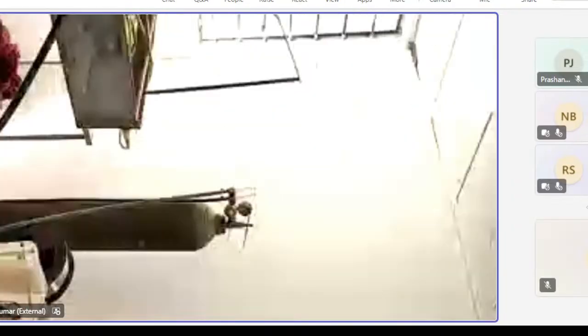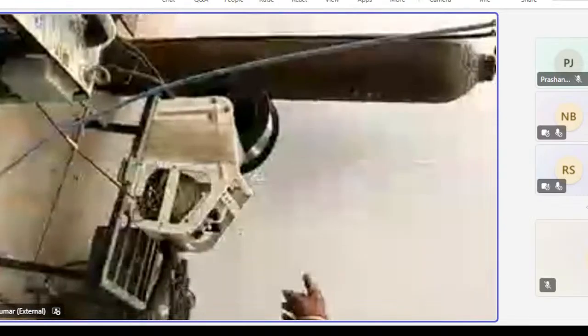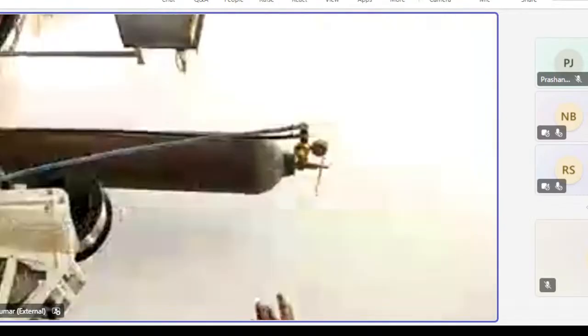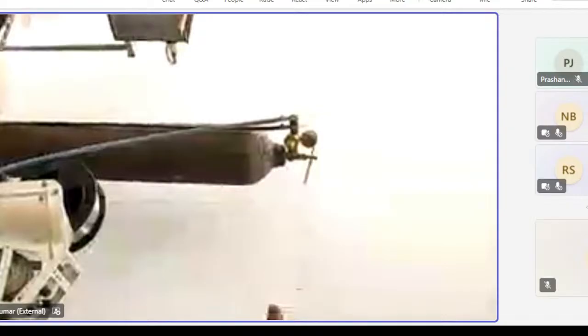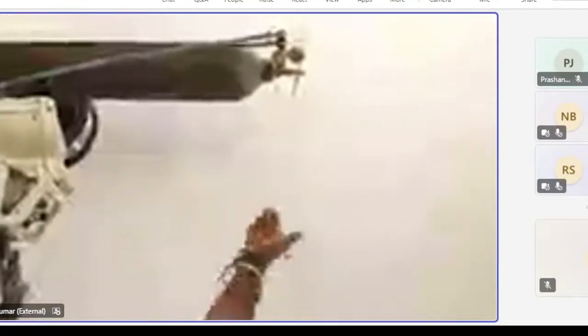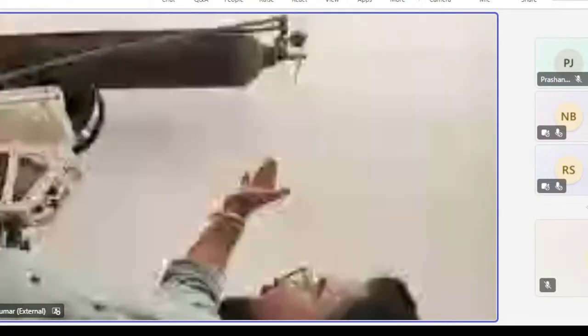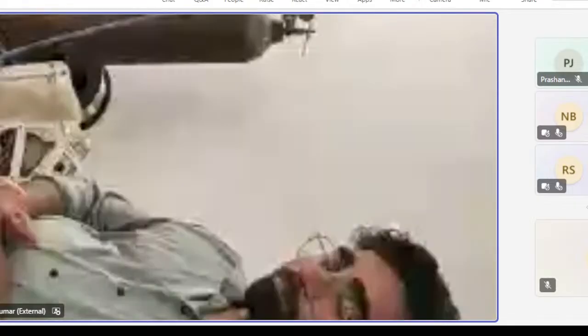Now, the fourth part is shown over here. That is the wire feeder. And the fifth part is the shielding gas cylinder. In this particular case we are using 99% pure argon gas as a shielding gas. Notably, this particular machine is designed for twin wire arc additive manufacturing.